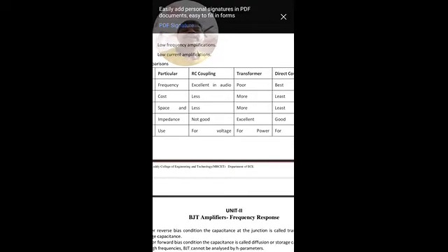The space occupied by the three types of amplifiers: the space occupied is less in the RC coupled amplifier. It is very high, more, in the transformer coupled amplifier because we are going to use transformers, so they are bulky, so this occupies much more space. And the direct coupled amplifier is least in space because of the use of fewer components in the circuit, absence of bulky coupling devices; the size is least among the three.